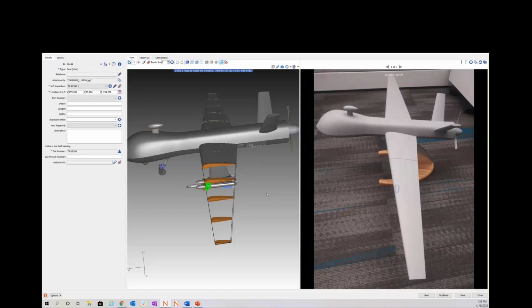Another thing you can do is, let's say you have a standard set of cameras you use out on the shop floor. You can add those cameras to the NLign database, and there's some meta information about the cameras that will help it align faster. If it can recognize what camera the picture was taken on, you only need 4 points to get it to align, not the typical 6. So that can also save you time as well.